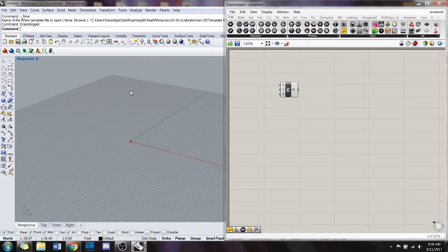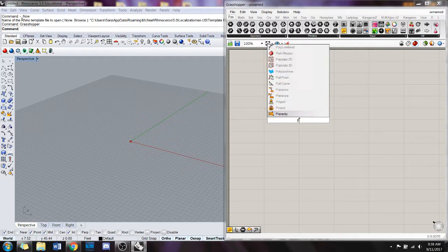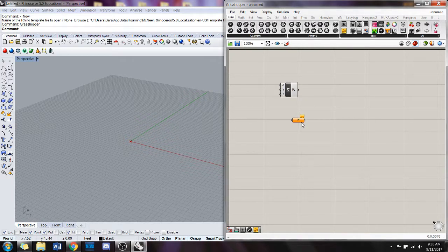Does it look like this, just orange? Then it's just a point. So what she's asking is if it looks like an orange box, does it look like that? Yeah. So if you get that, it's not actually a component. It's not running. It's got a floating parameter, point failed to collect data. It has no input, so it can't output anything. This is a point in Rhino.